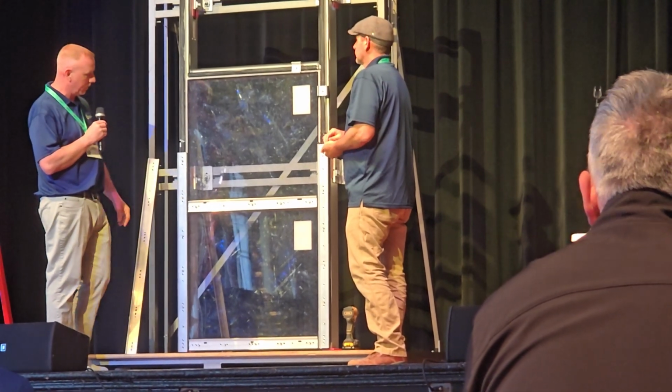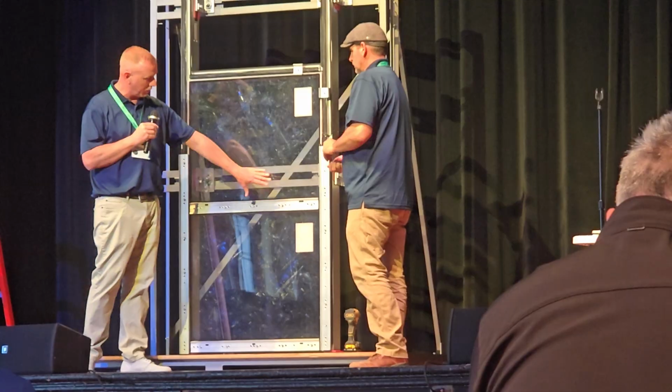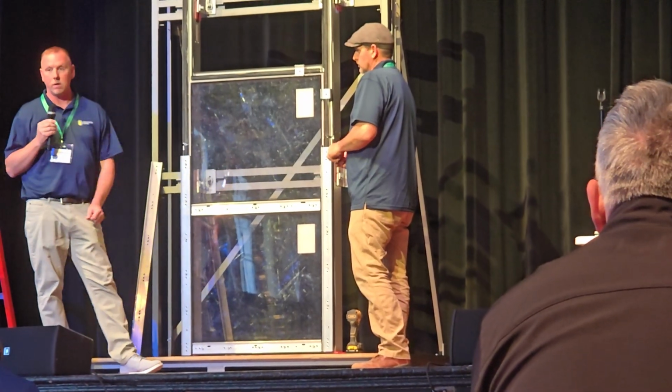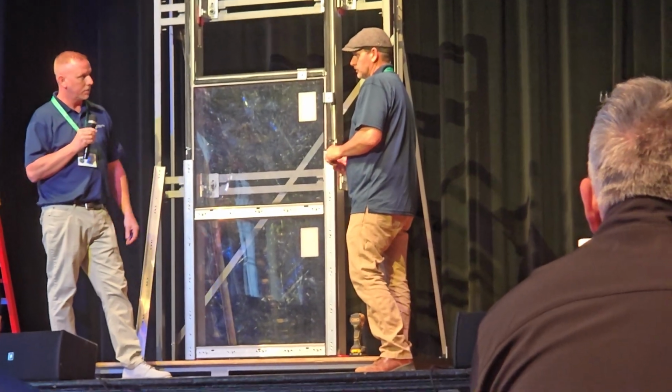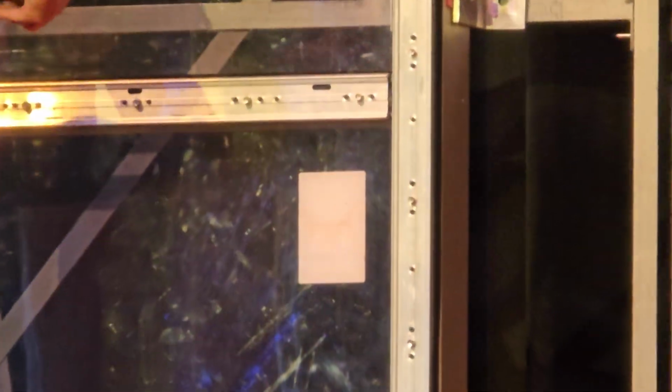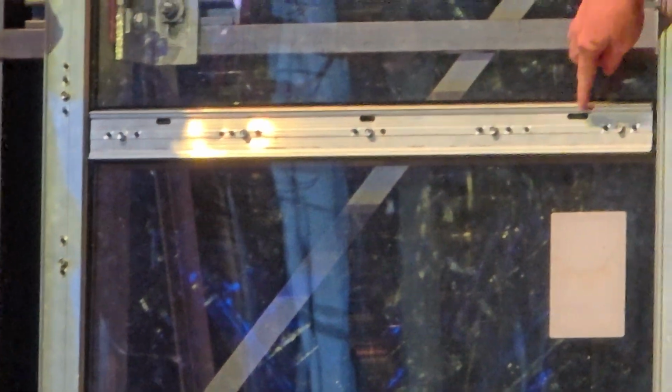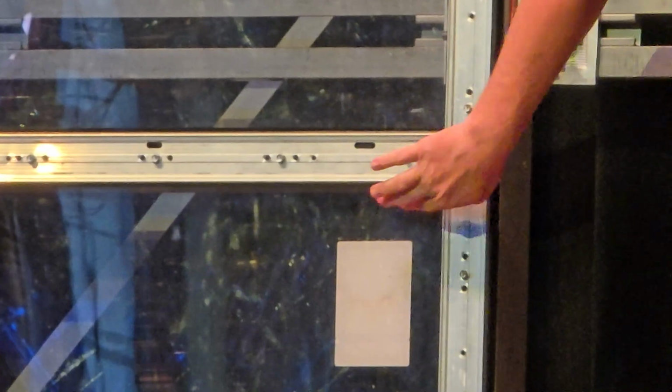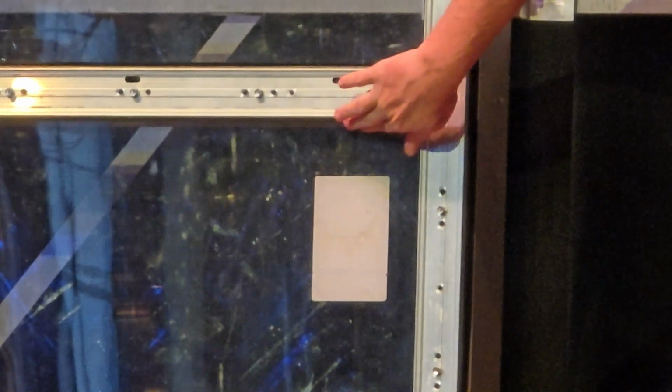Once all the screw heads are covered and everything's there, you've got to make sure your weeps are up, then that's when you start applying the covers. We're not going to install the covers today for demonstration purposes. Like I said, they're basically just aesthetic, but those cover plates will have weep holes, and those weep holes will be opposite. Once the water falls through the zone and out the top weep holes on the pressure plate, the weep holes on the aesthetic cover plates will be at the bottom, so it can find its way out.